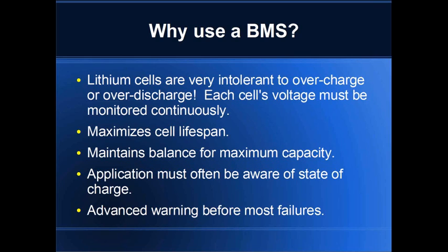But in reality, that never happens. Even the best balanced battery packs, there's going to be some minor differences in capacity. You're going to have some differences in internal resistance and internal self-discharge, so they're eventually going to unbalance a little bit. So in the real world, that just never happens. And one other thing to keep in mind, even if your battery starts out perfectly balanced and perfectly matched, eventually the cells are going to age differently.